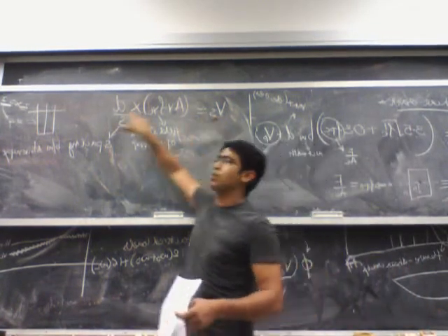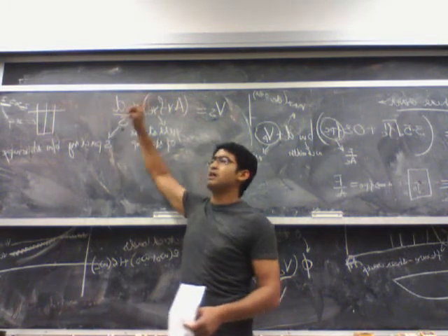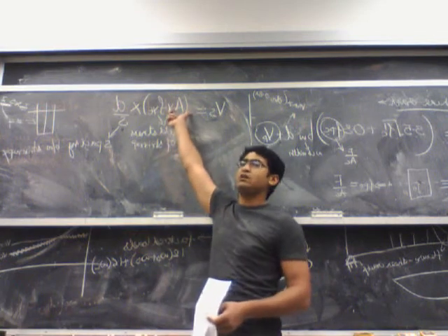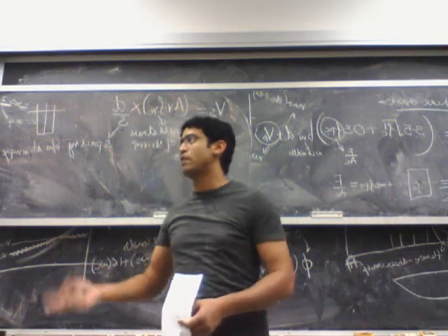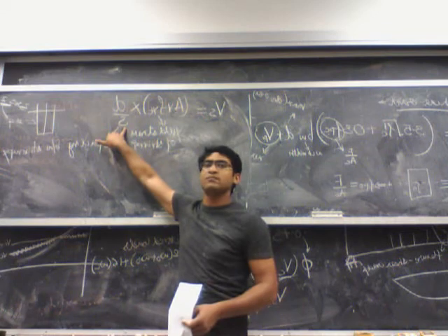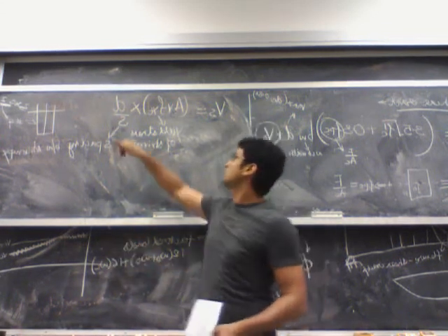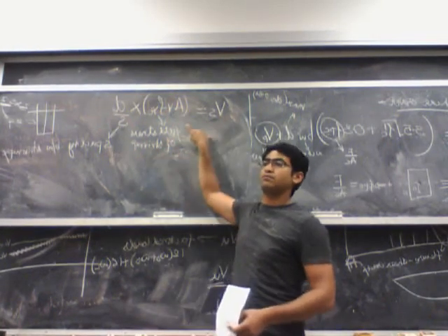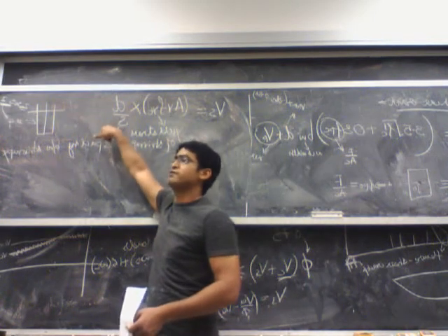Now you have one equation and 2 unknowns, Av and s, but only one equation. So what we do is either pick the value of Av to begin with. So you say, I'll try to provide 2 legs of number 3 stirrups. So you fix the value of Av and find the value of s. Or you can say, okay, I want to provide a spacing of 12 inches. So you pick a value of s and find the corresponding Av which will satisfy this equation. Generally people pick Av and find the value of spacing.